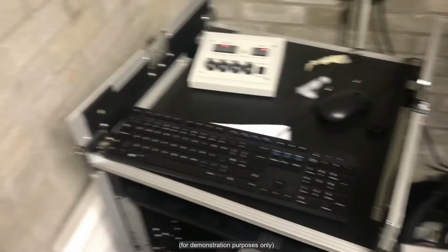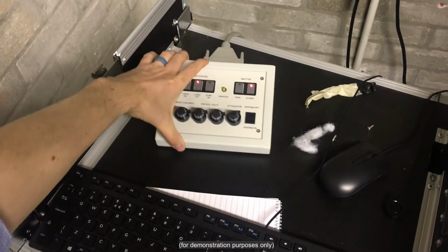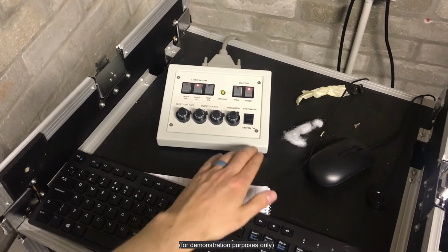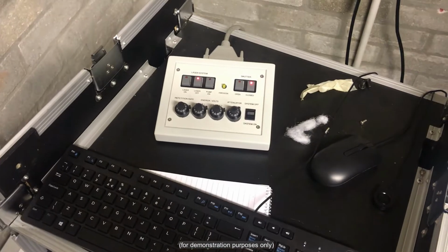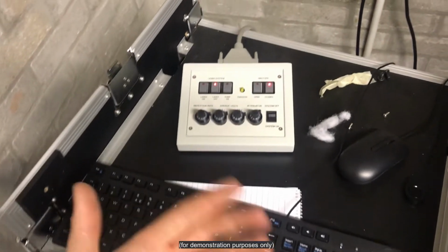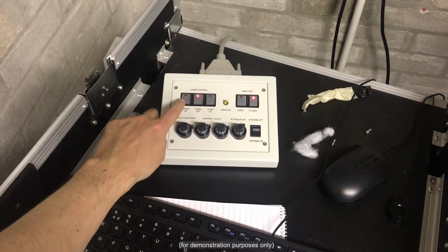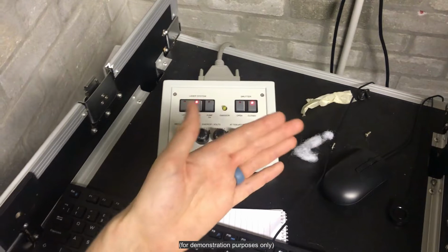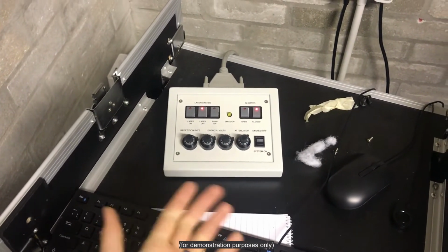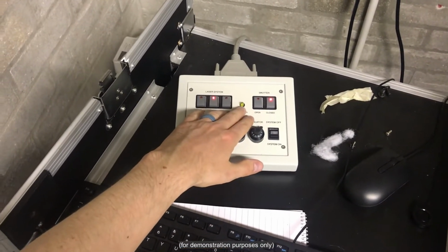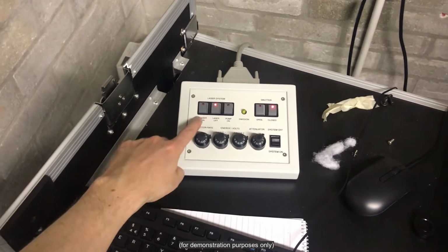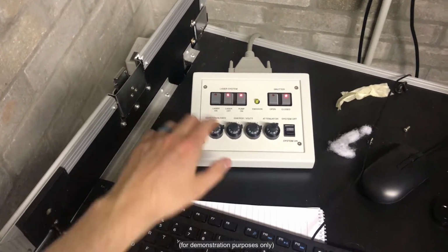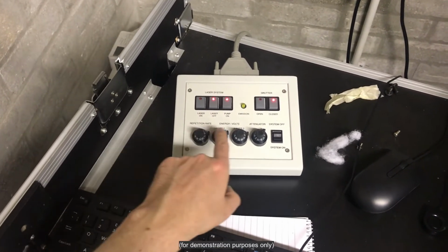What that means is we can control the system using this control board, and if we want to fire the laser, we need to firstly switch the system on, which is what's done here, and the system won't fire. I could try and tell it to turn the laser on, it won't do that. I can open and close the shutter, which is kind of like a door that allows the light to go through, but nothing will be emitted, and when there is an emission, this light will come on. To fire the laser, the pump must be on. The pump, as you can hear, is now on, and all of the settings for firing are set by this.